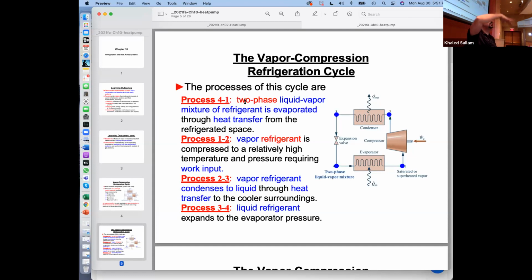Why is it better than this? Because when you're doing something like this, you are heating or cooling with something that is lower than the lowest point. So at the beginning, when you were doing this with that, there's a big temperature difference. That's not nice from the thermodynamics second law. When you're using something very hot to heat something cold, that's not a great idea. That's why a lot of cycles get better by doing something called multi-effect. They divide it into small parts, and every part gets to exchange heat with something closer to it.